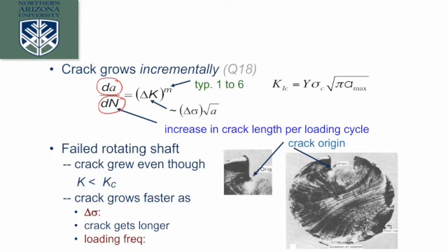As we cycle the material, the length of the crack will increase. And this increases by the K value, the toughness value, to some factor, right? So essentially, stress changes with the crack length. So we can use this to estimate at different values, and we can use this to determine how it changes as we cycle it through multiple fatigue cycles.